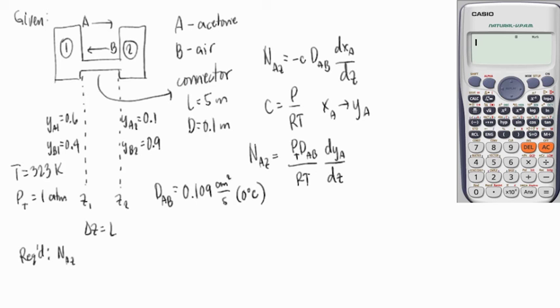Going back, our conversion equation is simply a ratio and proportion. We write D1 P1 over T1 raised to 1.75 is equal to D2 P2 over T2 raised to 1.75. D represents the diffusivity, P the pressure, and T the absolute temperature.